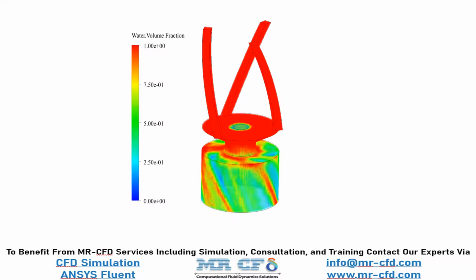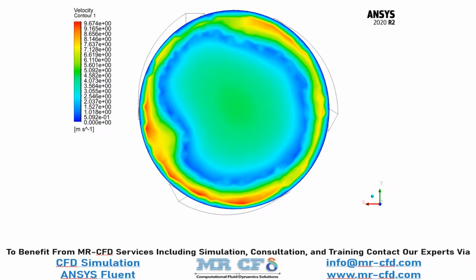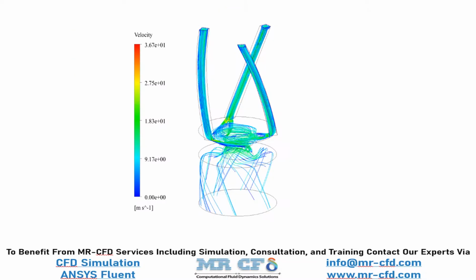Now in this 3D contour, which is related to the water volume fraction, you can see that water flows through 3 branches and then enters our cylindrical computational domain and is sprayed through this domain. Now in this 2D contour, you can easily see that the water flow is injected almost in the middle section of our outlet boundary. Now in the streamlines contour, you can easily see how the water has spread and injected inside our cylindrical computational domain.